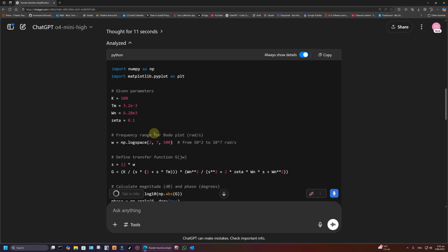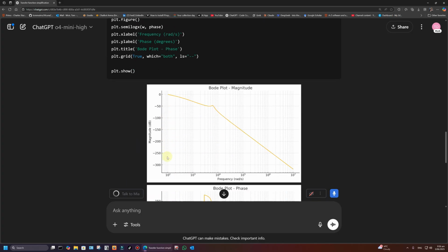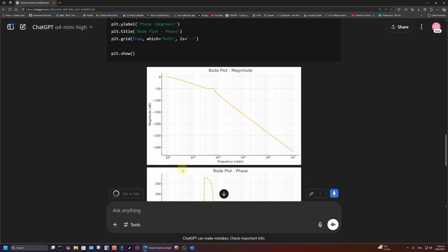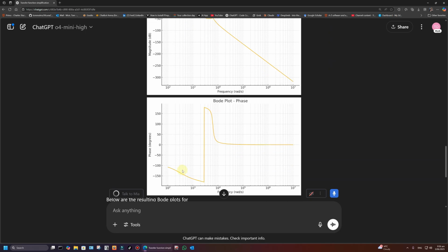So it's doing this numerical calculation, and not only that, it's going to plot my frequency response, and it plots it, and it's pretty much spot on. This is the example I used in my textbook anyway. This phase, by the way, is what's called wrapped phase. Nothing to do with music. It's wrapping, meaning just to get it in the graph, it's flipped by 180 degrees. So the real phase goes from about minus 100, goes here, and then it keeps going negative all the way down.